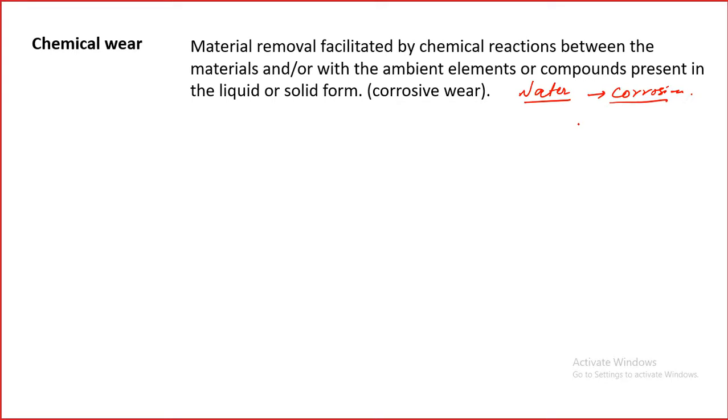So all kinds of tribological contacts are subjected to corrosion. Any tribological system you take will be subjected to corrosion. Therefore, in our solution, we have to always take care of the corrosion. So material removal facilitated by chemical reactions between the material and the ambient environment, or elements and compounds present in liquid or solid form, is also known as corrosive wear.